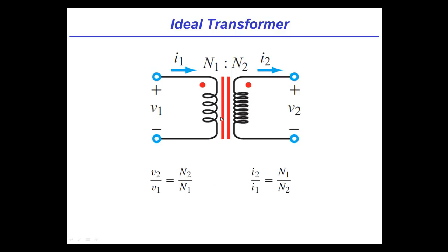So, Michel, let's say I wanted to reduce the voltage from 120 volts to 12 volts. So that's a change of 10x, right? Yeah. So I want V2 to be 10 times lower than V1. Then I want N2 over N1 to be 1 over 10. So does that mean I get, say, 100 turns on N1 and 10 turns on N2? Exactly right.